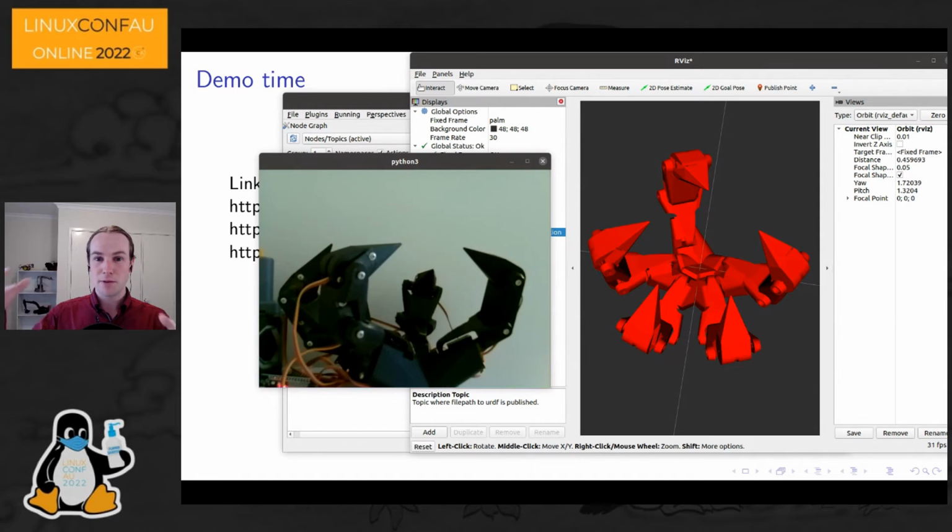You can have motion commands come in from a host system, with a default e-stop behavior if something happens instantly on the microcontroller. If the microcontroller needs to respond to an event quickly, you can do that on the microcontroller.